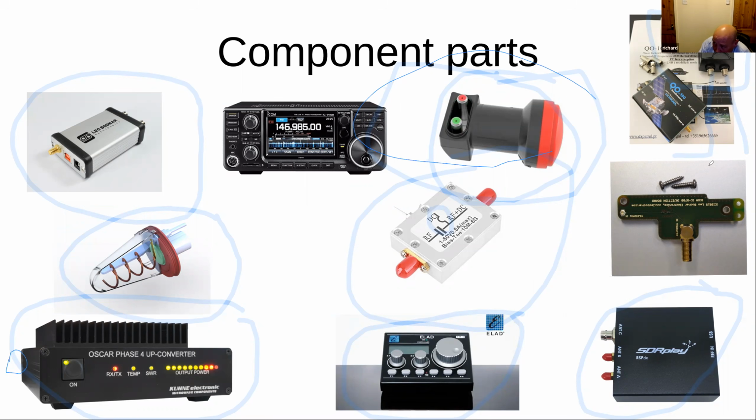And then one thing that I do need to do at some stage in the future is, I have got disciplining for the radio at the moment, but this is a board which could potentially give me better results as far as disciplining. And this goes back to what I was talking about earlier on regarding frequency locking. This uses synchronicity to effectively impinge directly onto the oscillator within the board. So it has a tight coupling onto the tank circuit of the main phase lock loop, and it can basically pull the oscillator. So it gives you better accuracy.